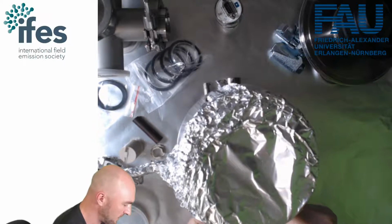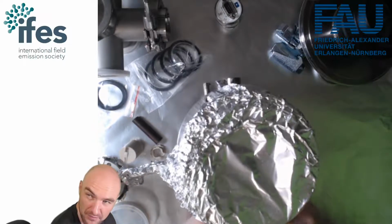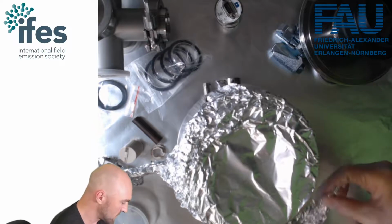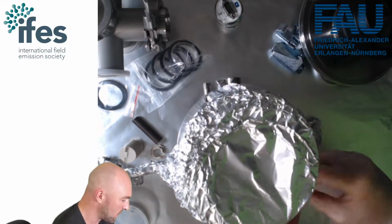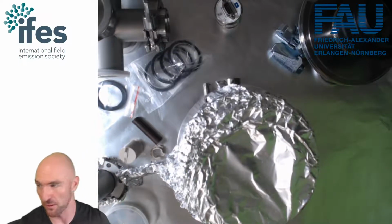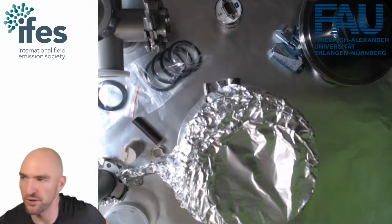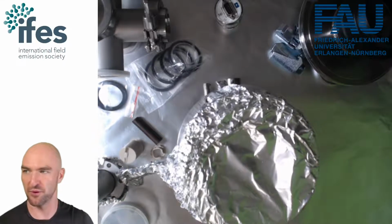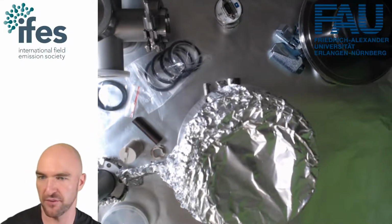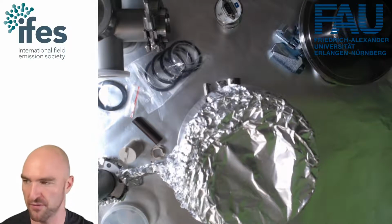And so you want to have the ability to put a little bit of gas into a turbo pump to slow it down quicker. Obviously, don't put too much in, otherwise you'll blow up your turbo pump. But if you get one of the approved valves from your turbo pump manufacturer, it will have the right amount of gas flow coming through it, so that you don't have that problem.